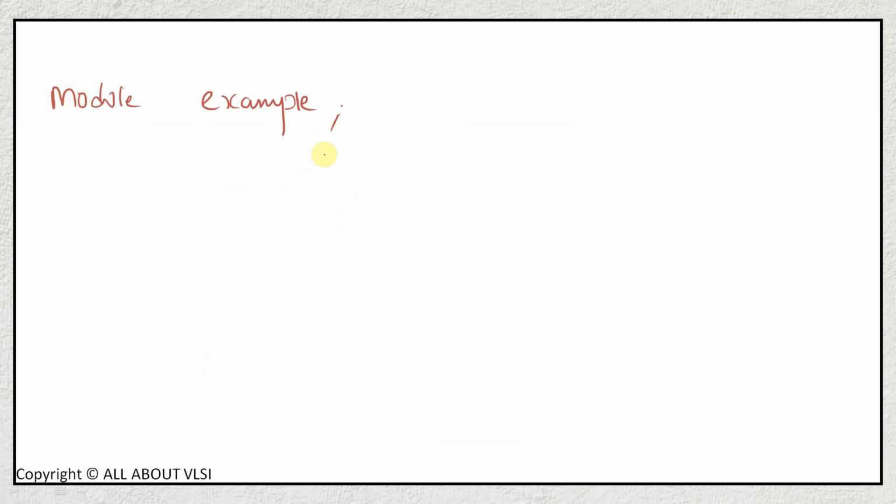Please remember, it is not necessary that you should always declare your input ports and output ports. If you are developing a test bench, then there is no need to declare your input and output ports. It is not compulsory that a module should always contain input and output ports. So in this case, we are not using any input and output ports. This will be your design with no input and output ports.